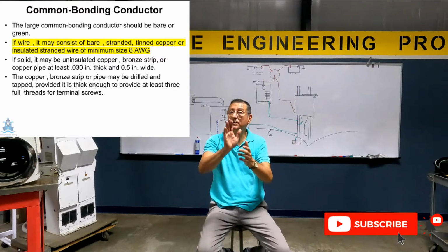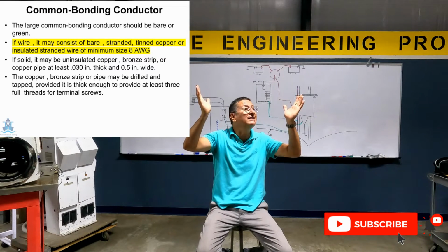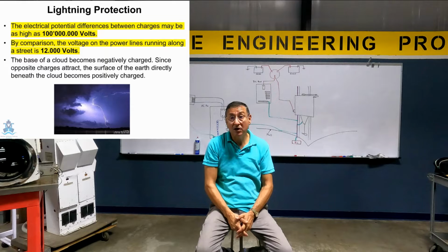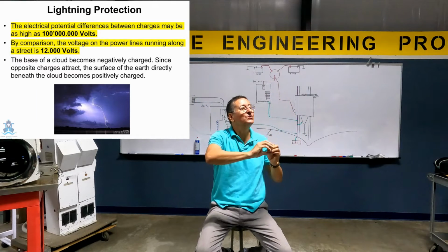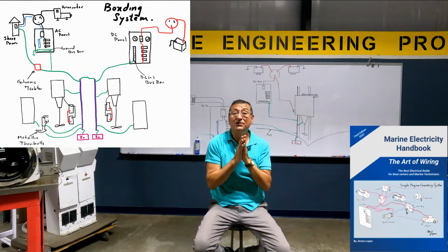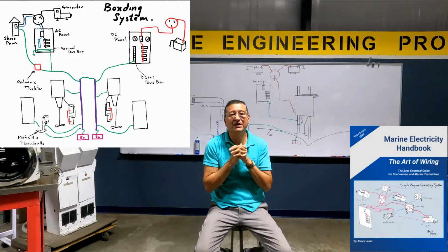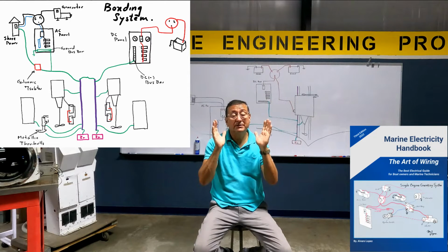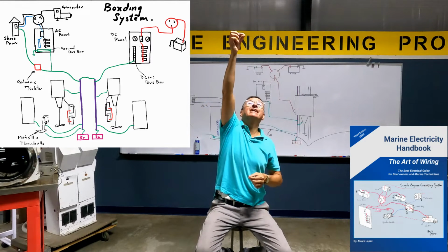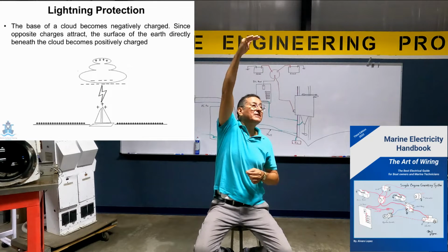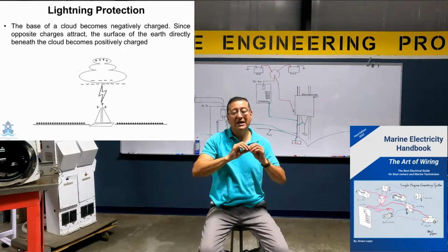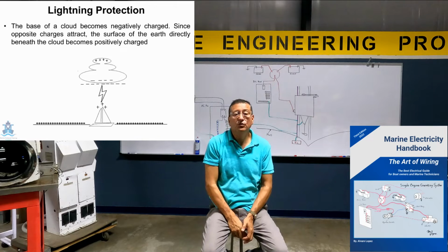What happens in the moment of a storm during lightning is a lot of voltage, millions of volts and high currents. Those currents are drained through the bonding, into the sink, into the water, and finito, bye-bye. For that reason, a good bonding system is necessary, it's mandatory. In sailboats, more, because you have that long piece of metal, and it's easy for the connection between the cloud, and if you don't have a good bonding, good lightning protection, you can destroy the boat.